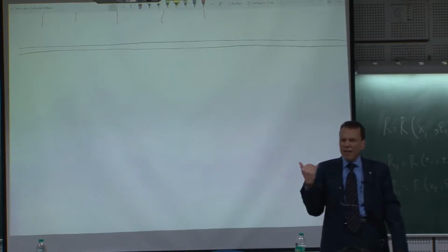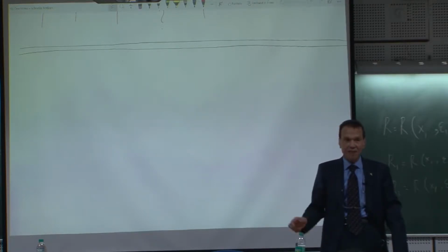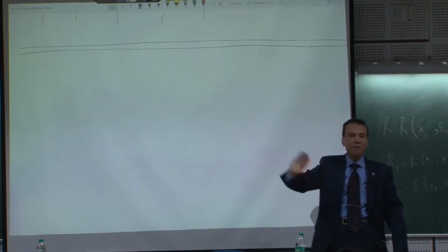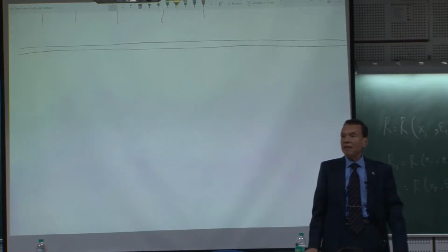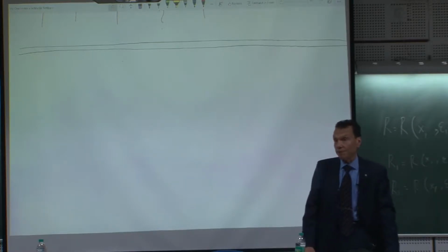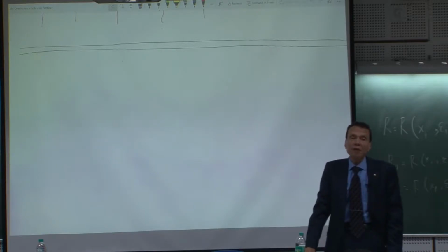anything which relies on the magnitude only is highly welcome, because you may use a very, very simple detector, which is a rectifier, but a fast rectifier composed of diode and capacitor, in order to follow the envelope. Okay, and in this case, things are much cheaper. But if you measure vectorially, of course you have to do many additional steps, which make equipment very, very expensive.